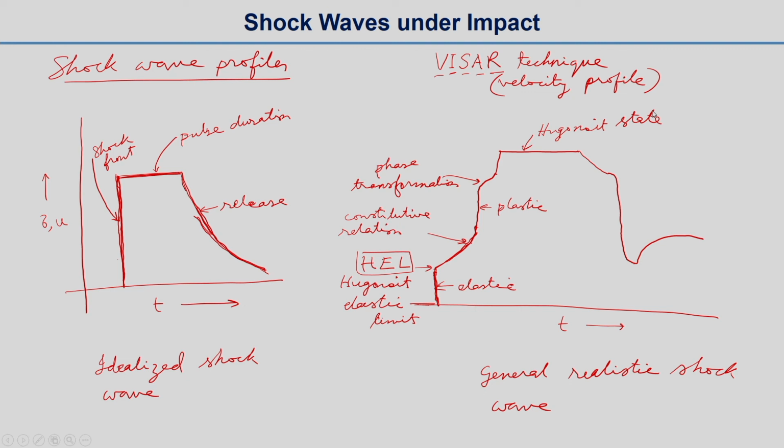And then the unloading curves, that is actually elasticity first, written as Hugoniot pressure elasticity, and then it will show plasticity in the later portion.